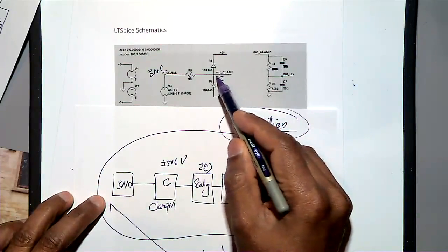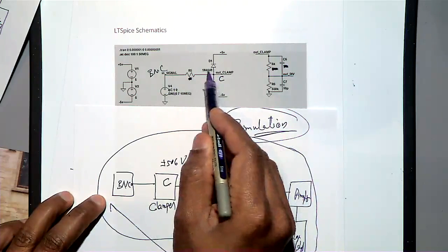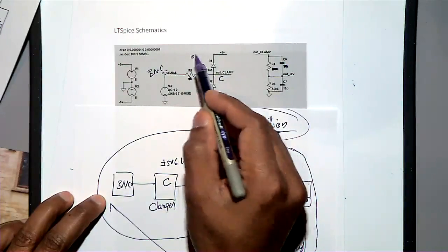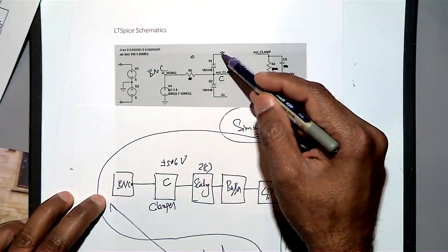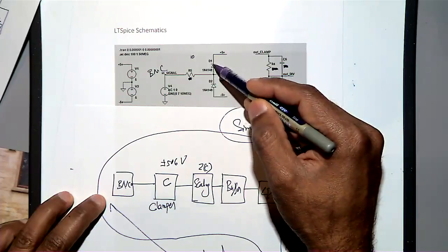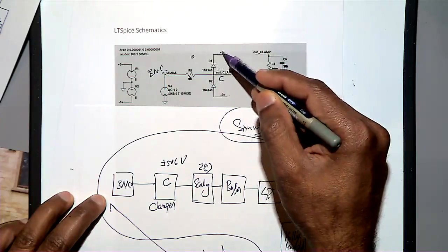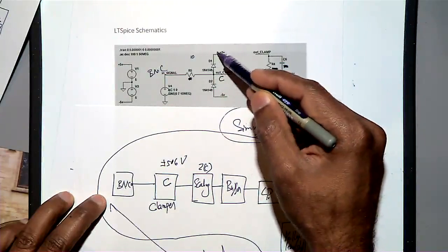So what it does is, suppose here, somebody connected 10 volt here. If it is 10 volt here, what will happen? So here I got 10 volt, and then here I got maybe plus or minus. So when it is 10 volt, this diode will be on, and then it is shorting with whatever the 5 volt here, so that this part will never go beyond 5 volt.